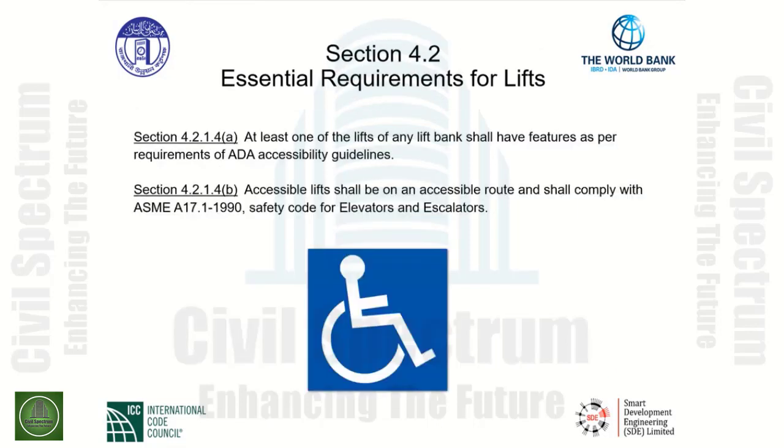Section 4.2.1.4 Item A gives us a reference regarding lifts. At least one of the lifts of any lift bank shall have features as per requirements of ADA accessibility guidelines.